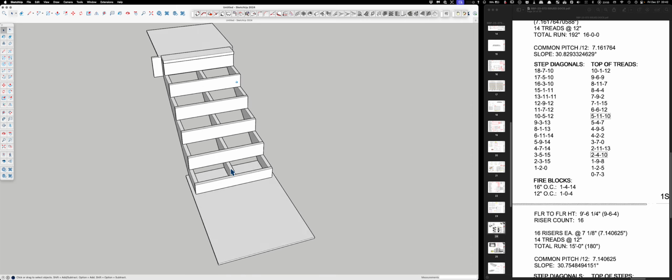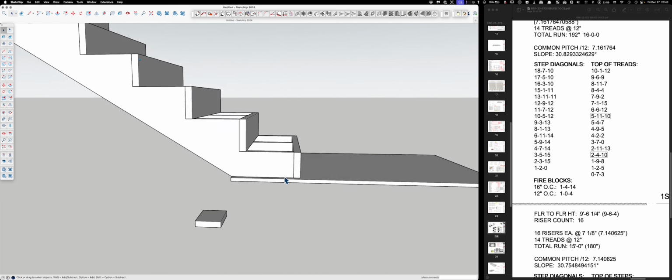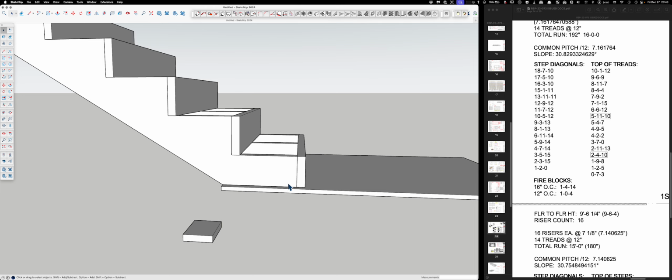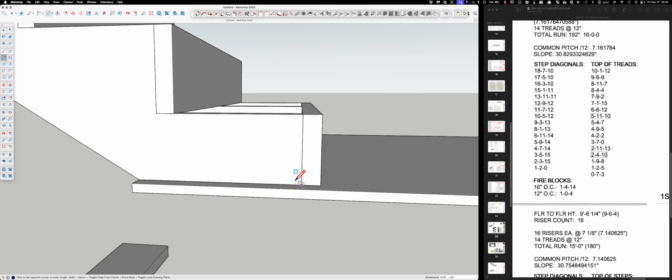And then while we're here, some people like to have a thrust block. I'm nailing into wood and I'm gluing into wood, so it's probably not really needed, but out of habit, I've just done it for so long because that's just what I was told to do whenever I built these as a younger framer.